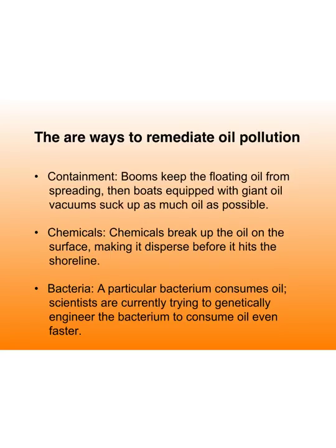All right, there are ways to remediate oil pollution. I would definitely recommend watching those videos because it's a lot easier to remember the techniques by watching it rather than just reading and trying to memorize, right? Okay, so containment, they use booms to keep floating oil from spreading. You can also use basically big plastic barriers and things like that. Some people try to use nets, but obviously it's oil, so it's going to get through a lot of it unless you come up with some material that's going to stick to the oil very well, right?